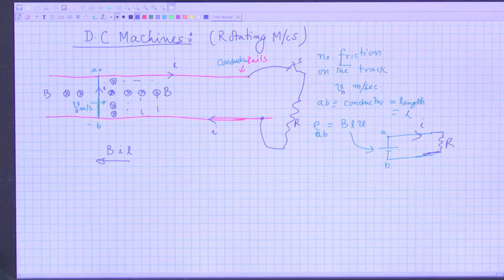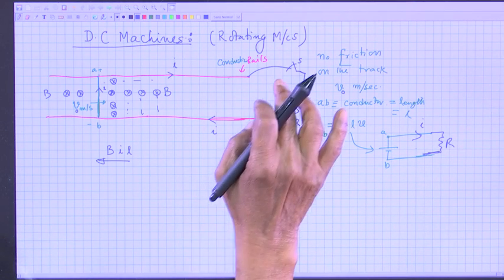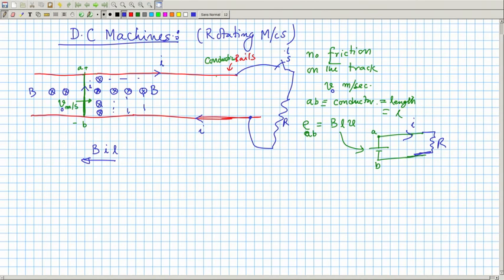It looks like that as time passes after you have closed the switch at t equal to 0, the magnitude of the current will decrease, the magnitude of the induced voltage will decrease, velocity decreases, and a time will come when velocity will become 0 and all this game will be over, everything will be dead. There will be no velocity of the conductor and things like that.